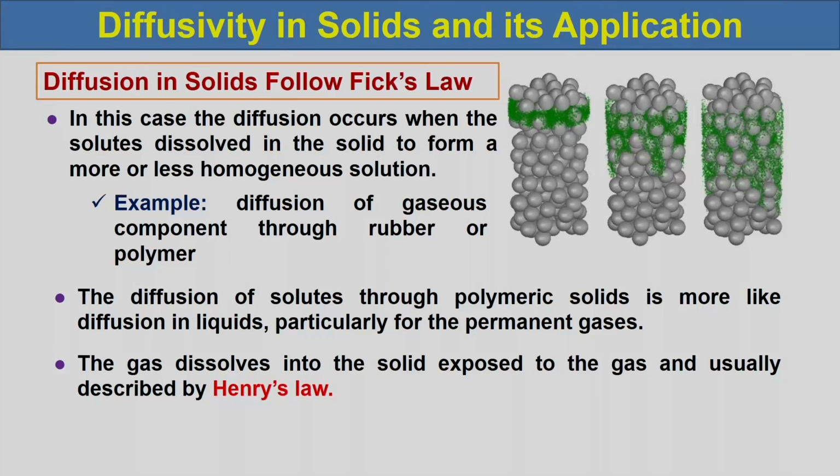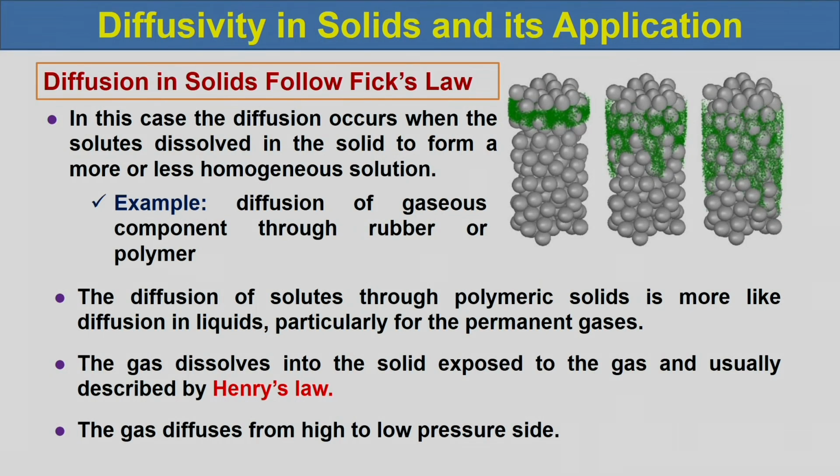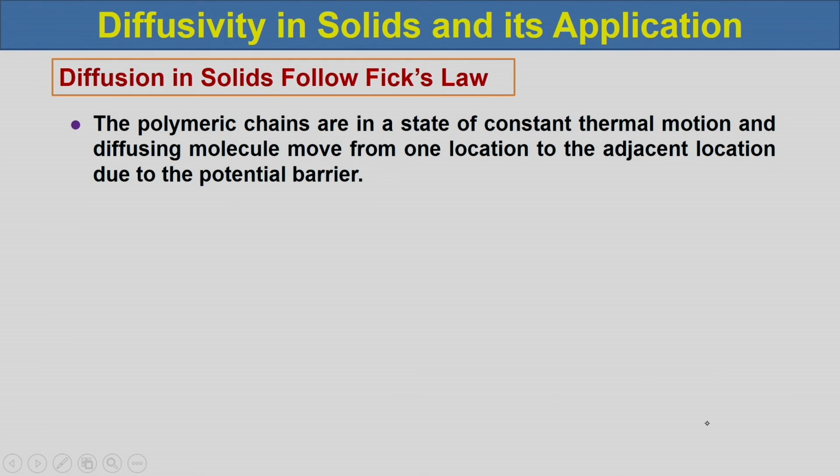So, in this case the gas which diffuses into the solid material forms a homogeneous solution, and the solubility of the gas in the solid obeys Henry's law. The gas diffuses from the high to the low pressure side. The polymeric chains are in a state of constant thermal motion, and diffusing molecules move from one location to the adjacent location across a potential barrier.